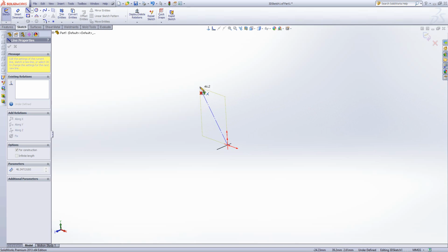For instance, if I look here, it can be difficult. If I rotate around here, you can see what orientation that line's being put into. If I hit the YZ now and have a look, you see the position's completely changed. And again, if I hit the ZX, even though the line looks like it's going upwards, I'm actually doing it inconsistent with the top plane at the moment. So just be aware of what orientation you're in when you come to sketch.